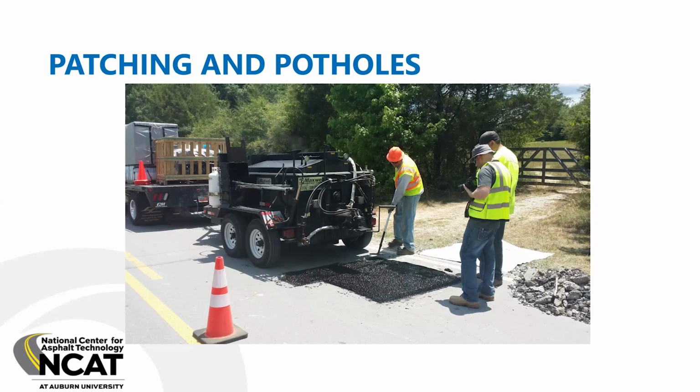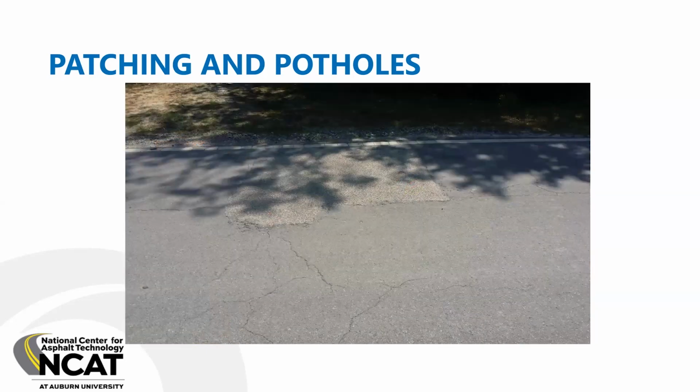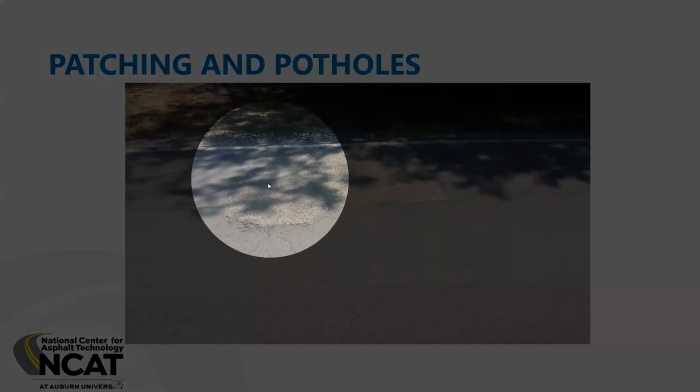This is a deep crack repair, and we had tried several hot mix solutions that had failed over this water line break. And so Maxwell Products came in with their highly polymerized mastic, and just kind of as a demonstration for us, they patched that pothole. And I think we're 7 years now after that repair. There's not a single crack in that pothole patch. So that's outstanding performance.